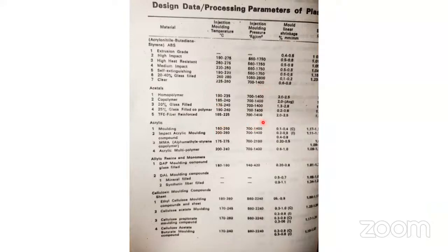See the pressure is constant here in this case for all, because Delrin is a material you can easily melt, but I told you it's difficult to flow, friend. Again, see the shrinkage here, higher shrinkage. Why is this shrinkage higher?